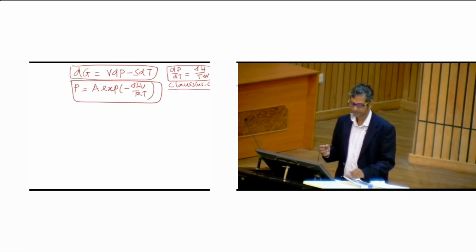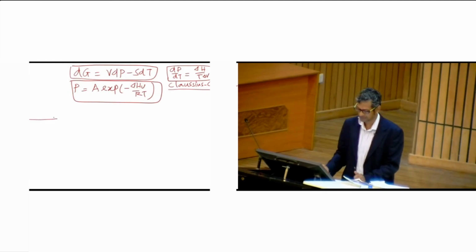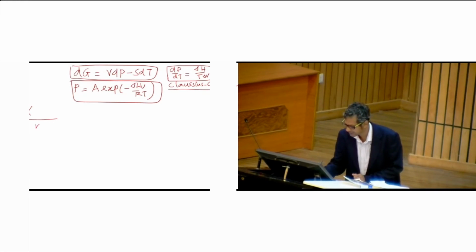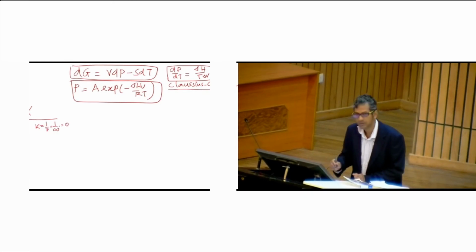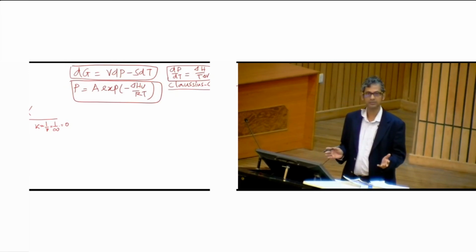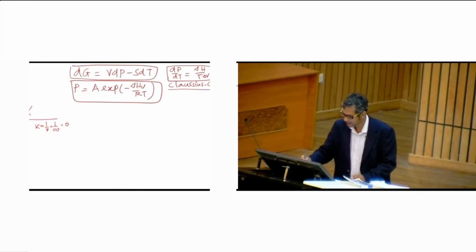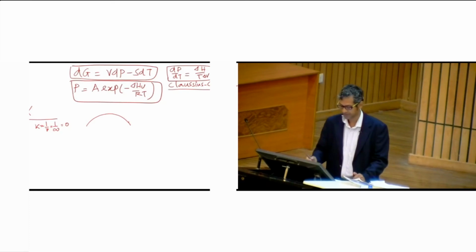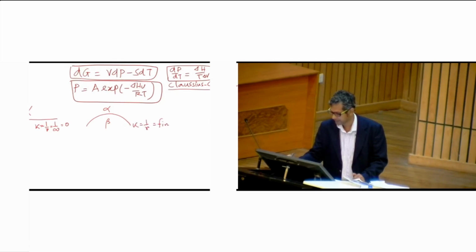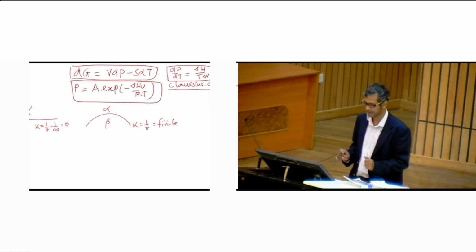As you know, if I consider a flat surface, and we are considering equilibrium between again alpha and beta phases, flat is defined as curvature, which is nothing but 1 by r, which is nothing but 1 by infinity, which is nothing but 0. Correct? We have defined curvature, right? For flat, curvature is 0. Now I consider a concave surface, again alpha and beta. Here curvature is 1 by r and this is finite, this is not 0.